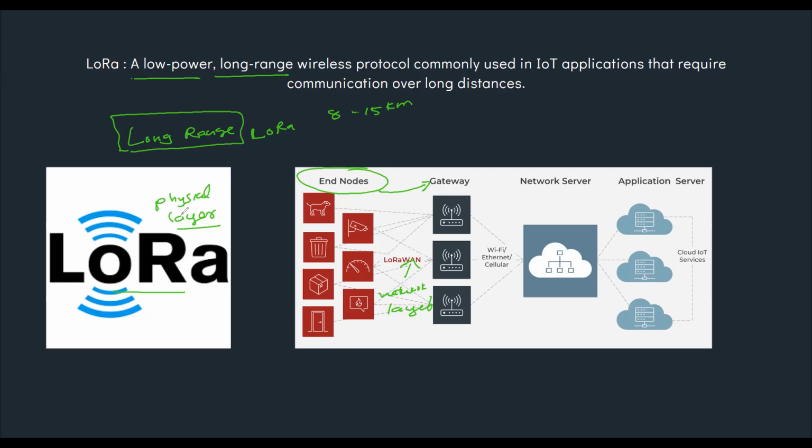As we are talking about IoT systems, it is very important to know these unique technologies that help in IoT communication. LoRa is one of those that has long range communication, and it has inherent technologies that it uses to reduce power consumption while also doing reliable data transfer. They are using technologies such as spread spectrum, using a wider bandwidth to transmit data while using low power over that bandwidth.